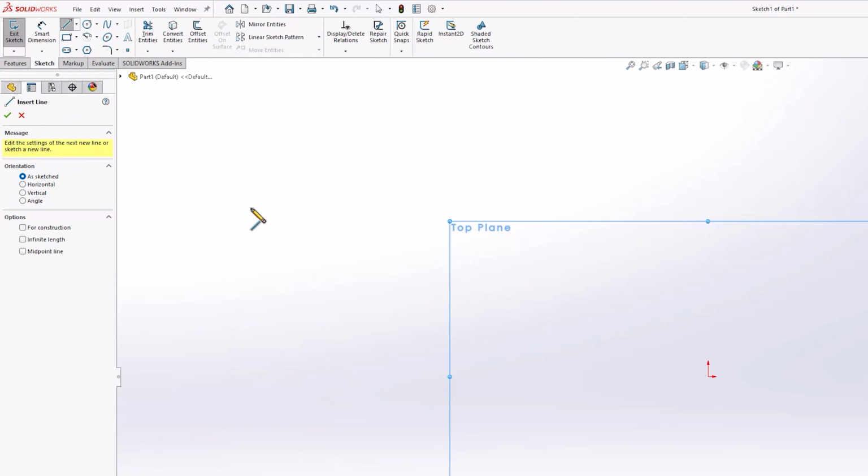Slightly later on, we will look at adding dimensions to our sketches. When the dimension tool is selected, the pencil icon is replaced with a selection arrow, and the dimension tool shown underneath. At any point, if you need to deselect a tool within a sketch, you can either click it again from the Sketch tab menu or tap Escape on the keyboard. The indicator that no sketch tool is selected will be that your cursor returns to an arrow.